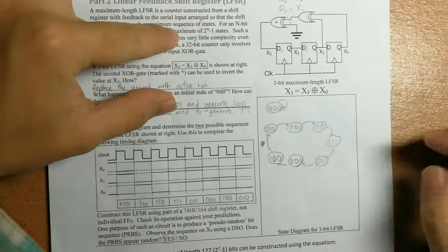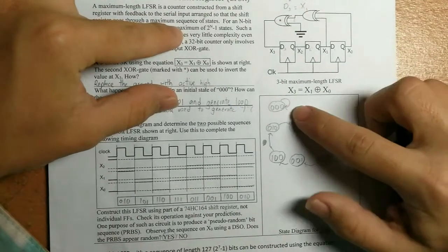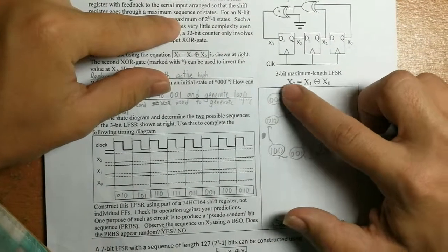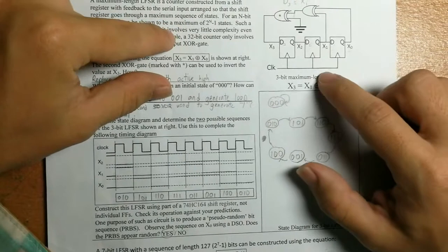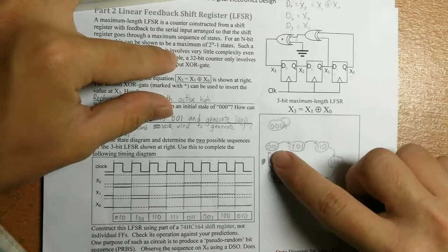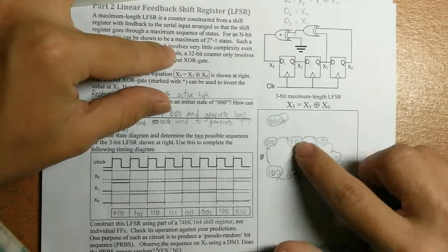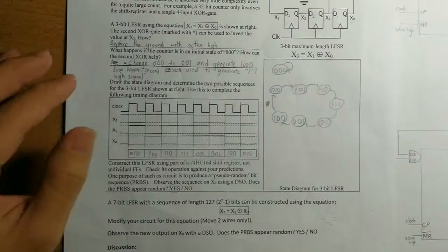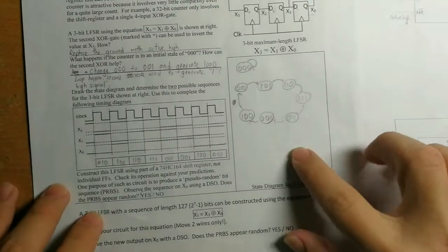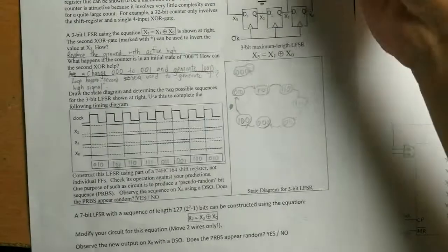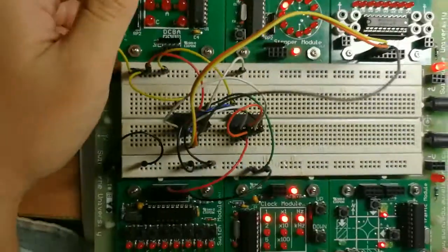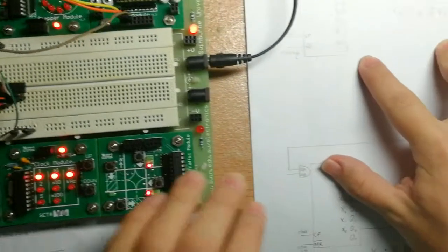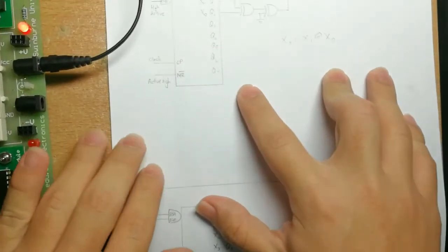For that loop, we can see from the state diagram, when S2, S1, S0 is 0, 0, 0, it will loop itself, and when the socket becomes active high, it will become 0, 1, 0, and form another loop in the state diagram. To prove the state diagram, we have to build a circuit, and this is our circuit. We have drawn a schematic diagram to show the circuit we're building.